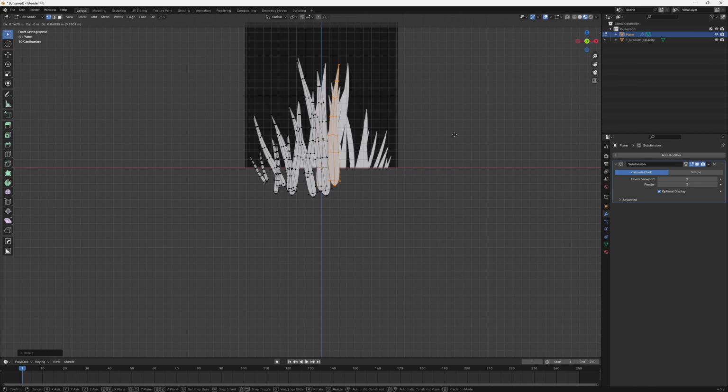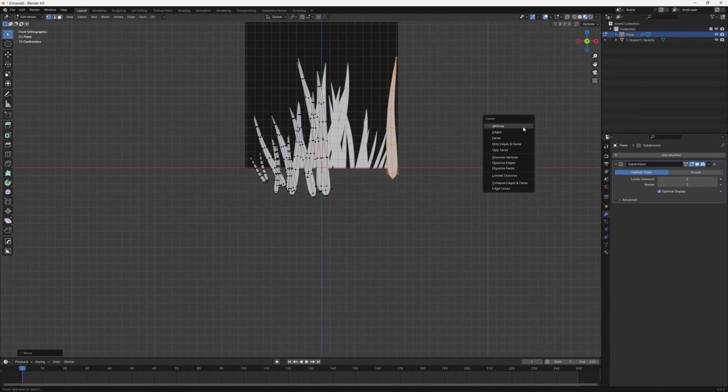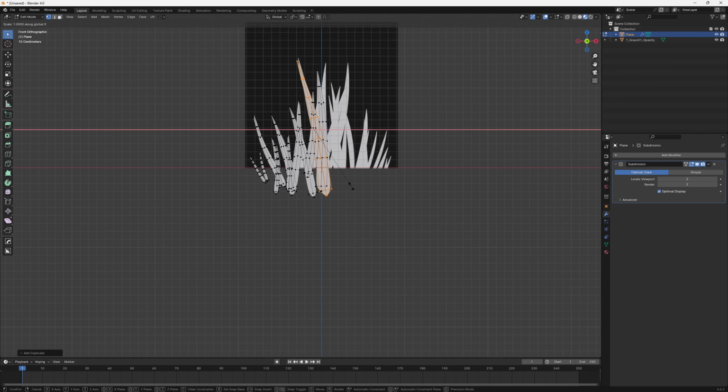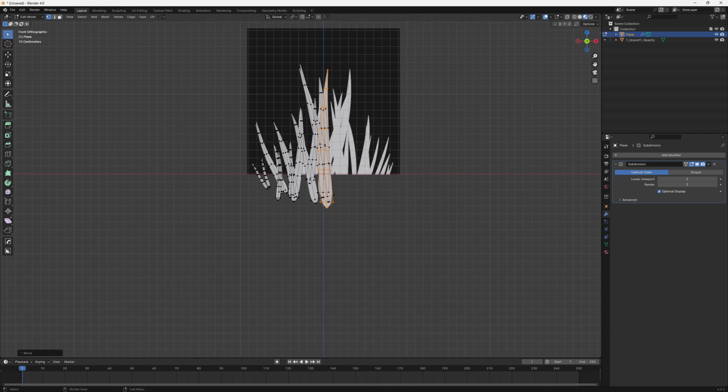I should be a little more generous to Blender novices as I am going in rock and roll mode on this, so I'm going to tell you exactly what I'm doing. I'm going to let you catch up. When I press L and I press G, L selects the whole mesh and G allows me to move it. When I press S, I'm scaling it. And by pressing S and then selecting an axis like X, I can type in a number. And when I type a number such as -1, I have flipped it on the X axis.